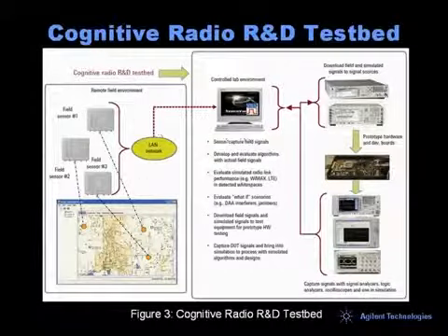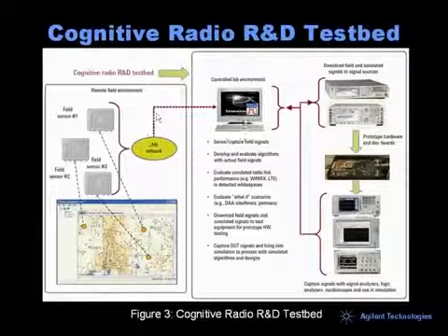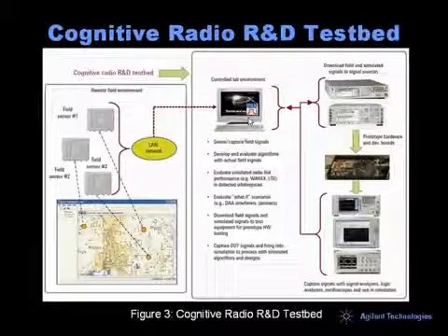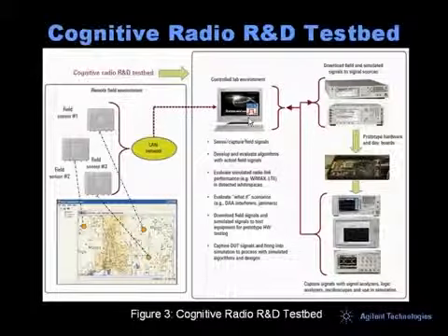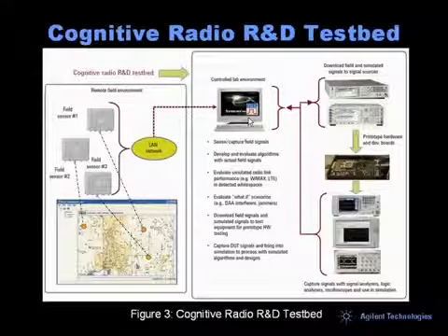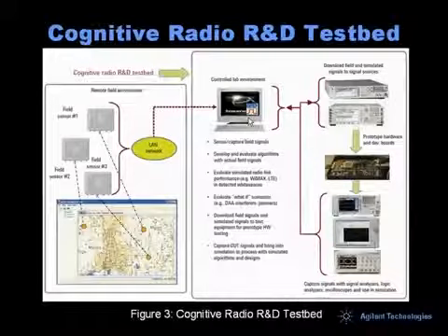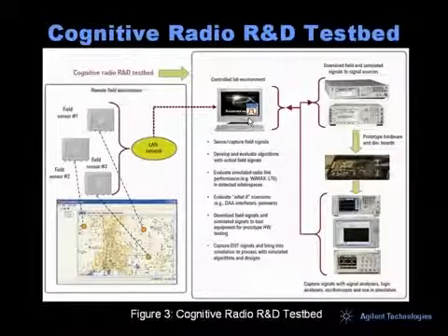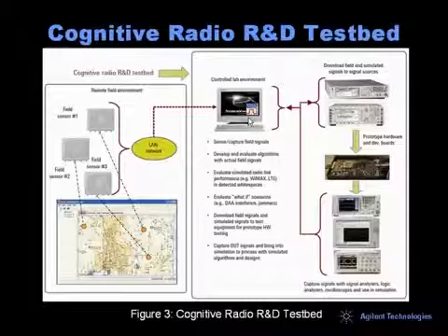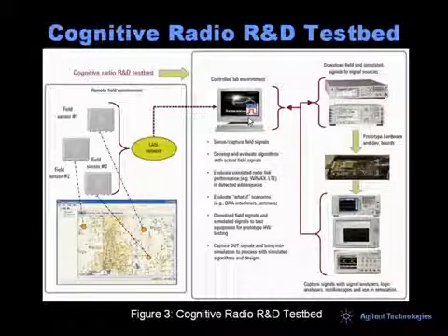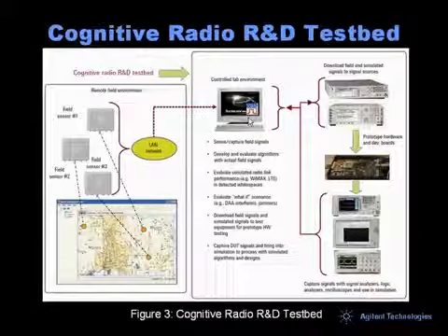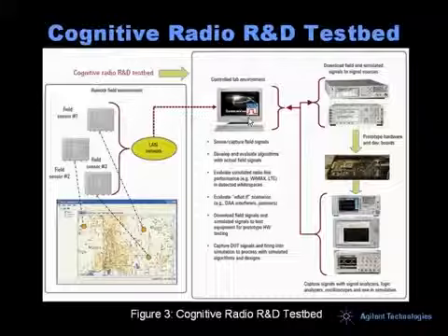The lab portion of the R&D testbed utilizes Agilent SystemVue simulator to capture the cognitive radio environment data from the remote RF sensors. Once that data is brought into SystemVue, SystemVue's math language and math language debugger can be used to write and test cognitive radio whitespace algorithms with the remote field captured signals. The OFDMA simulation modeling capability in SystemVue can then be used to configure and evaluate OFDMA mobile WiMAX and LTE link performance. It can also be useful to download and store remote field sensor data to test equipment for hardware DUT testing in the lab environment.